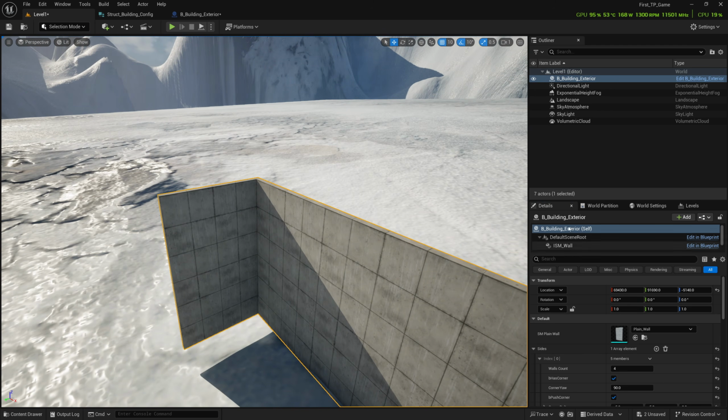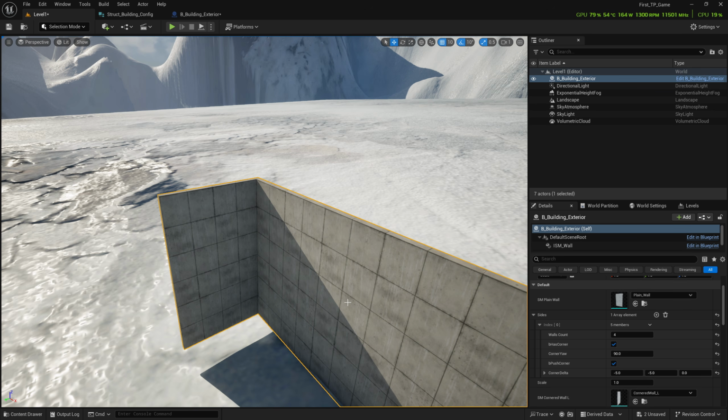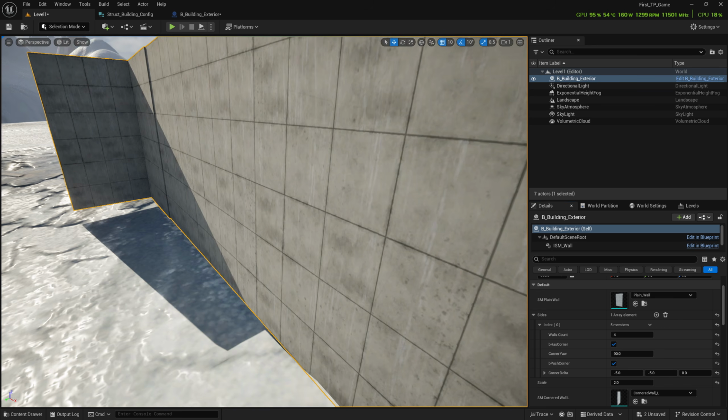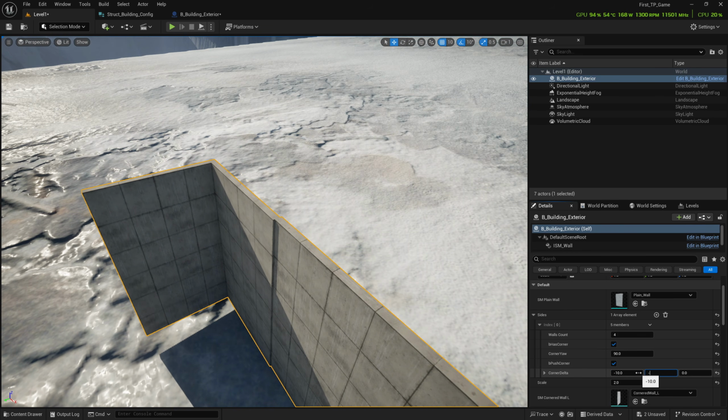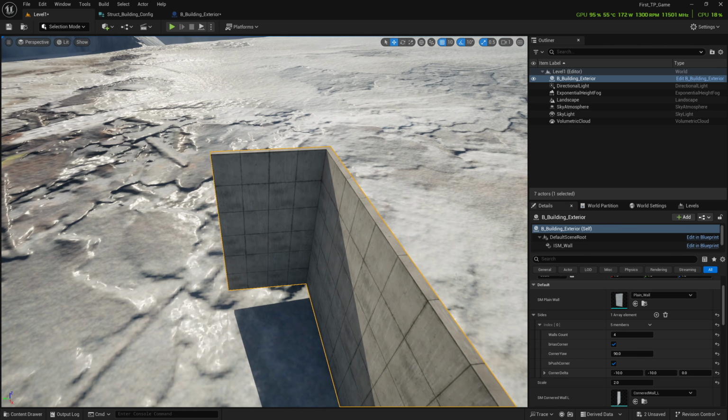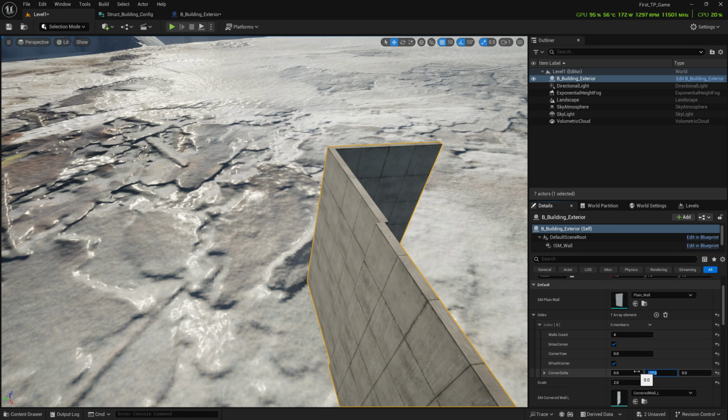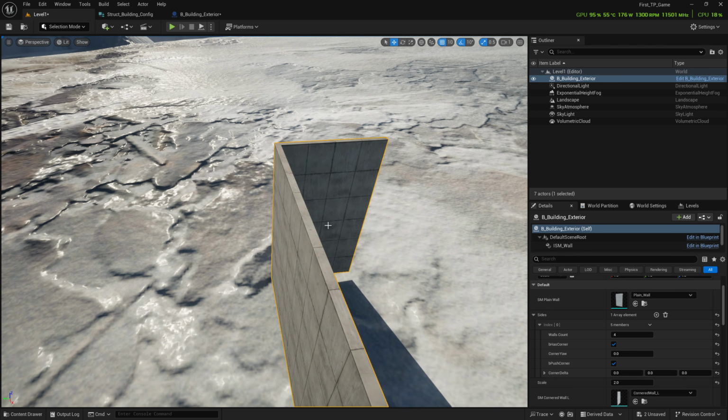One is you can directly scale the actors. Another way is you scale the wall. So I'll go for 2 scale, little bigger walls. And now I have to change this to -10 and -10. Okay, now the corner is overlapping. And let's say if you change your mind and you want to switch to that direction, then you don't need this. So you set it to 0, 0 and everything is fine.